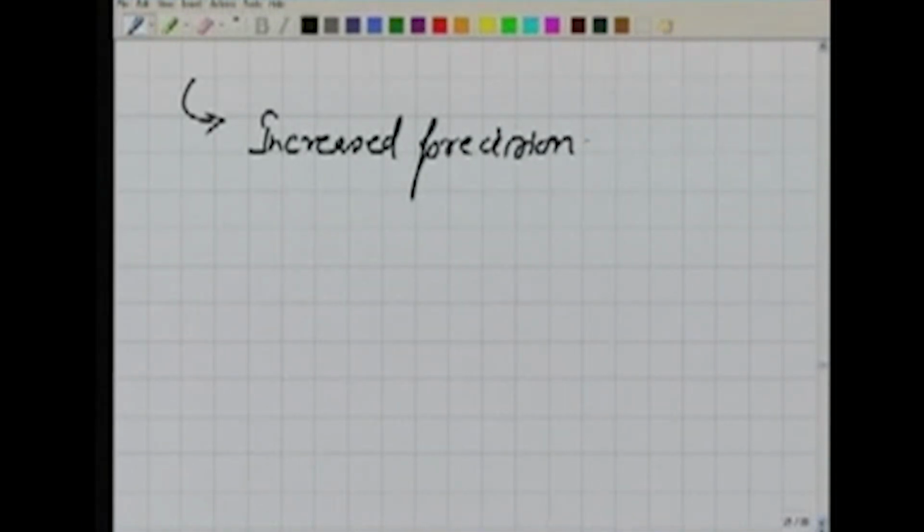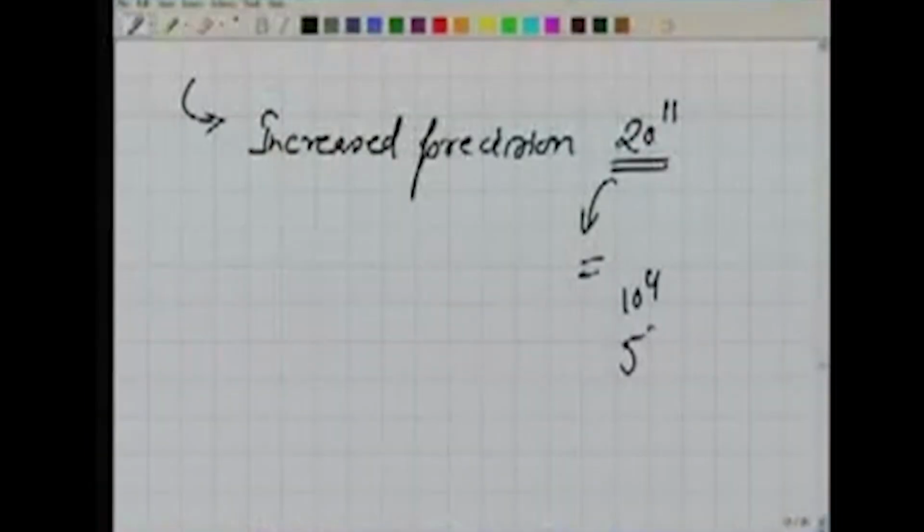What is the meaning of that? If our theodolite is a 20-second theodolite, the least count is 20 seconds. We improve the precision; we try to bring this further down, maybe 10 seconds, 5 seconds. We increase the precision by this particular method. Number two, we also eliminate some errors which are in the theodolite. We'll talk about these errors in detail later on.